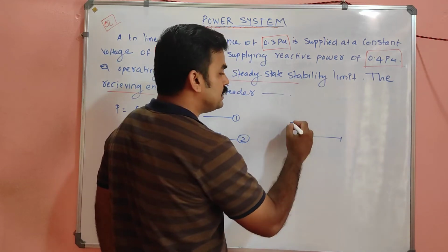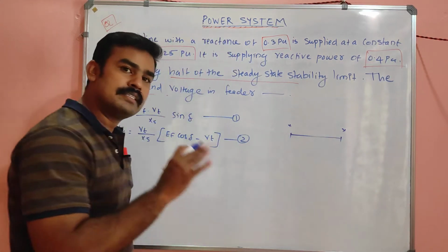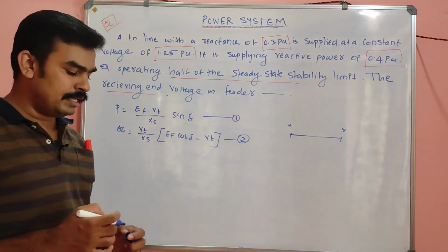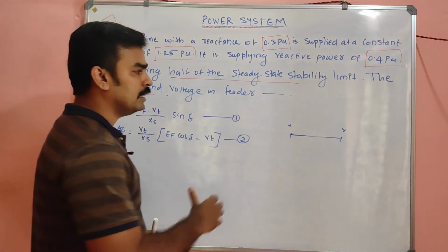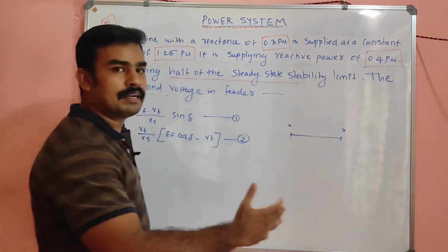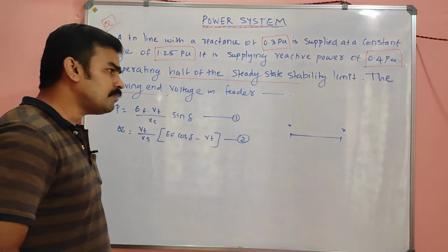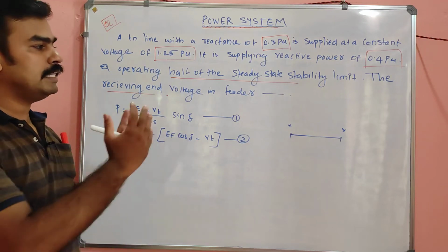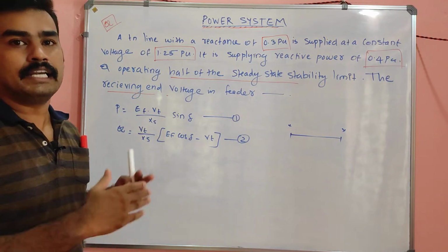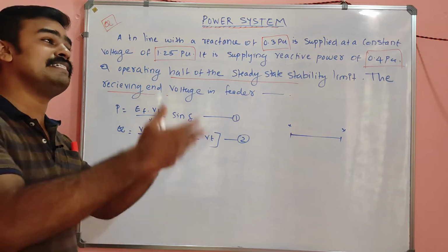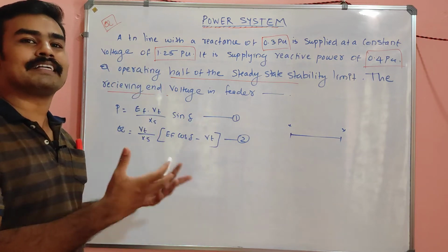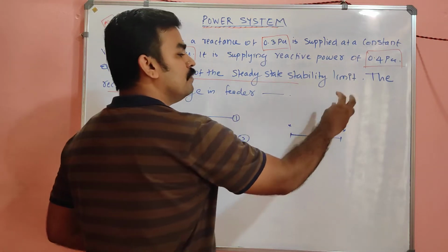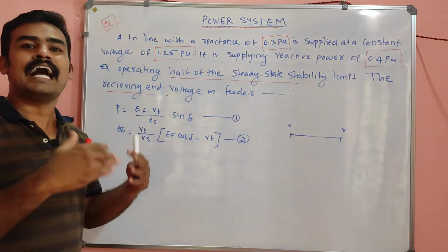These will not be the same, because due to the transmission line reactance there may be losses, so the voltages will differ. Sometimes the voltage increases, depending upon the power factor correction method used, but a bare transmission line will definitely have a diminishing output voltage.